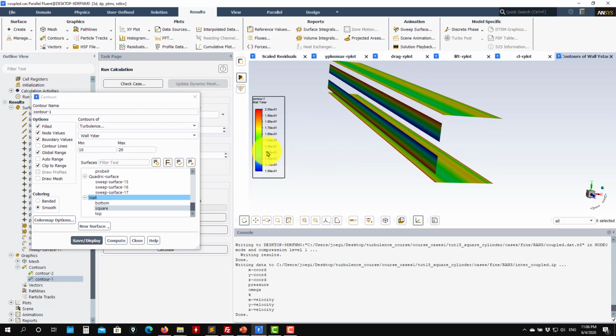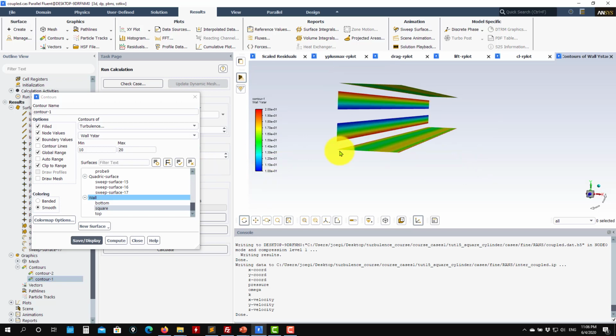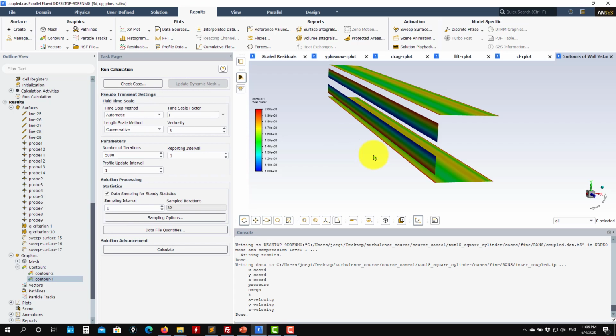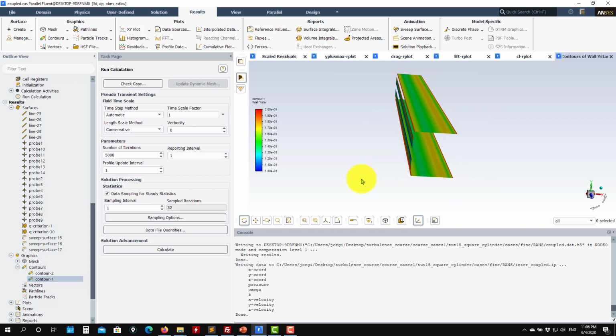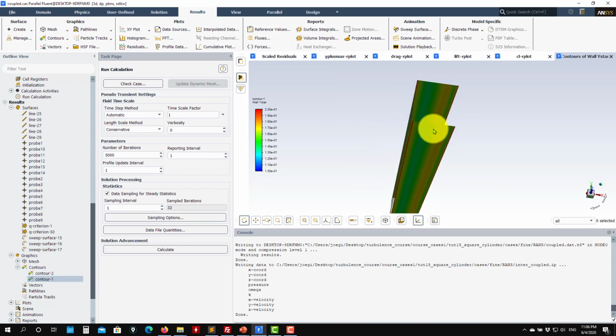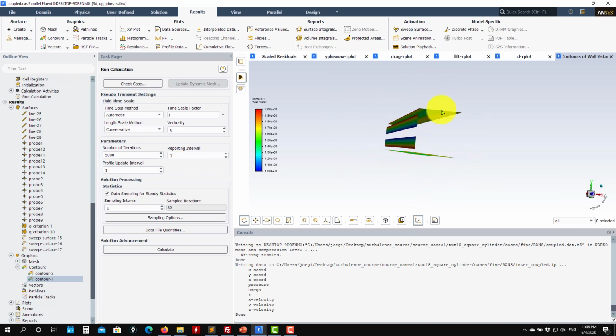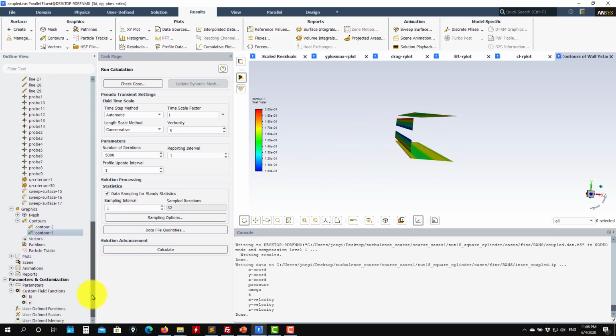So we have many cells in the 10 to 15 range, so not very desirable. But with wall functions, we know what they are doing. Fluent has a robust implementation, but let's say it would be better to have y plus below 10 or above 30. Okay, so if you have your geometry, you have the dimensions, you can get a better mesh. So now let's move to the unsteady case, and that's all for this tutorial.